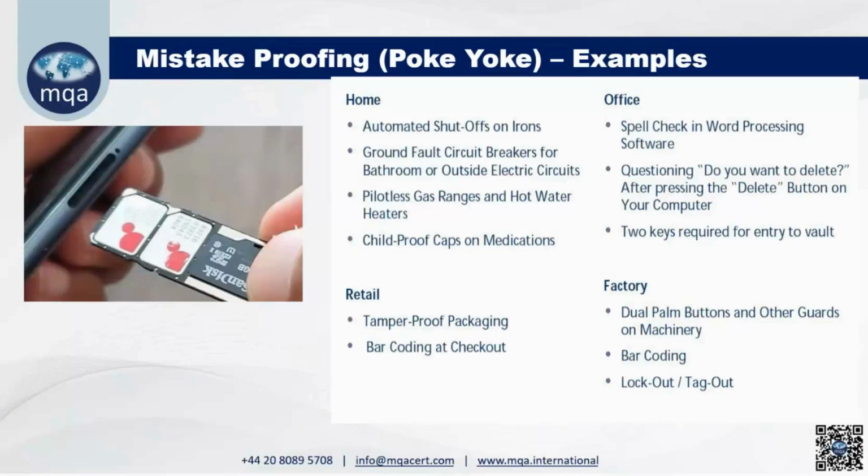There are different types of sensors available. Like photo sensors, which will detect human parts. If the hand is going inside the machine, the photo sensor will detect it and will not start the machine. This is also mistake proofing. Generally in the press shop where the tool is coming, and in forging, machining, wherever there are moving parts, it is required.